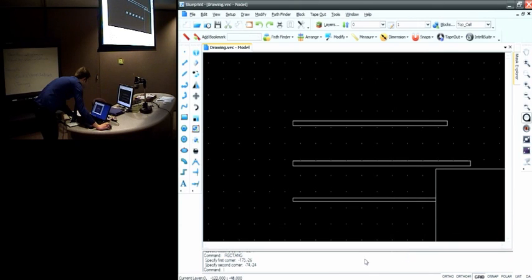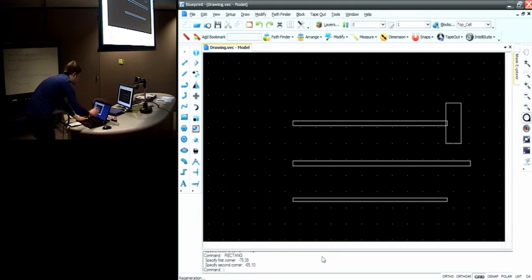Should be symmetrical. All right. Next we create an anchor, which will just be another rectangle. So we have 75. These can also be made by simply dragging from one point to another, and you're able to control the grid and snap settings to show where your mouse will stop.